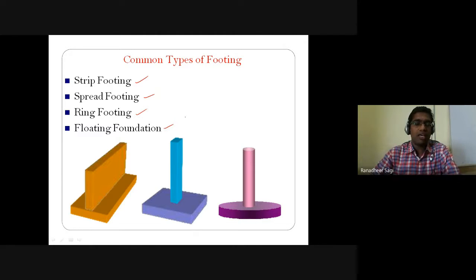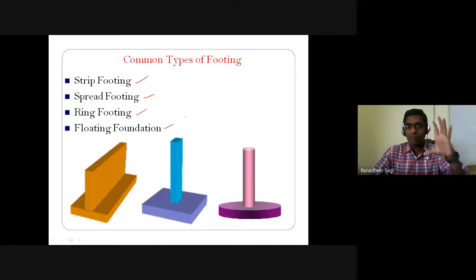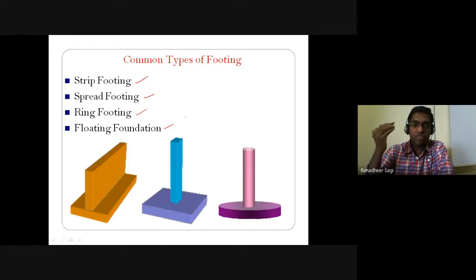After the construction of the foundation and the subsequent superstructure, if the load intensity transferred from that complete superstructure onto the soil is less than the load intensity of the soil you have excavated, then such a foundation, constructed to transfer the load coming from the structure onto the soil strata at the footing level, is called a floating foundation.